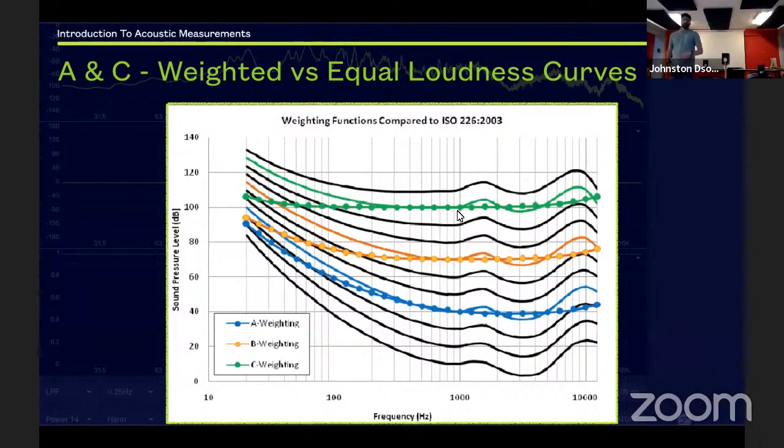Yes, sir. Okay, so these are nothing but filters that are added to the measurement itself. Your audio is captured by the microphone and it is sent for processing. When the processing is happening, these filters are added. That's why these softwares can give you two different readings by taking just one impulse in through one microphone. It will take whatever the audio signal is coming and process it in two different ways, one for A weighted and one for C weighted.